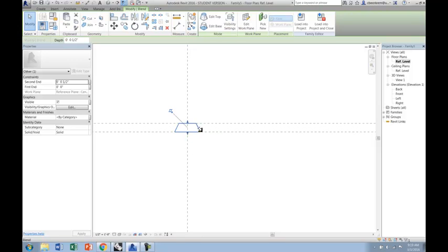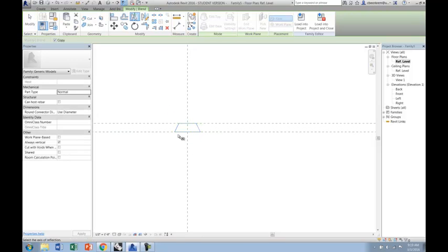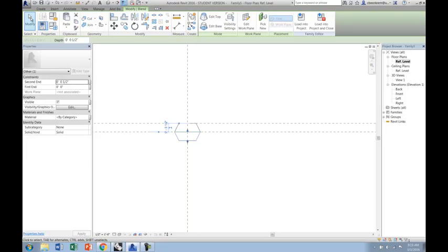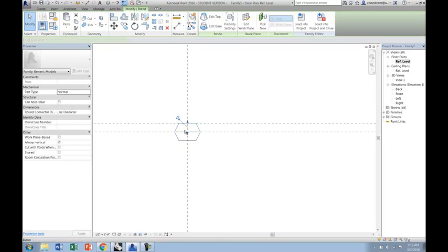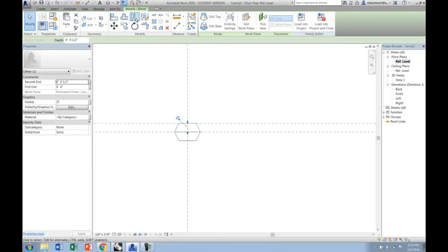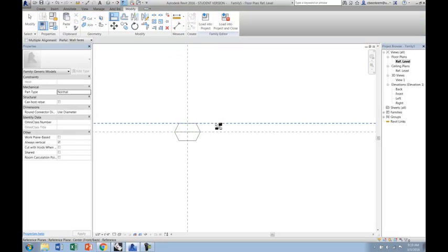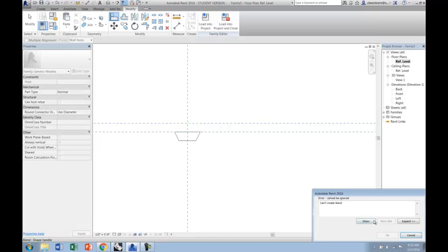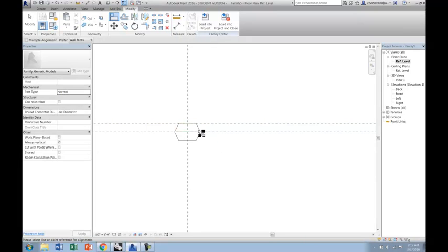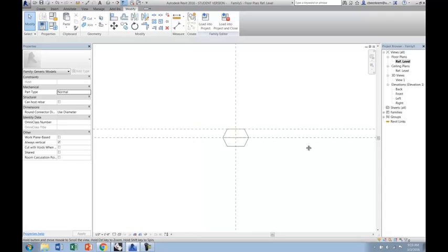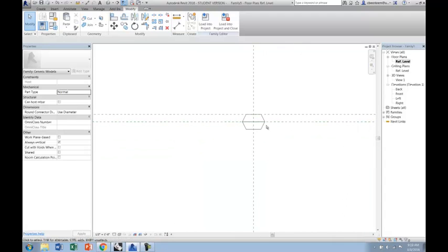So here's the first part of our knob. We're going to want to mirror this along that plane. And now we want to use the align tool, and we're going to use this align tool a lot. You're going to use that to make sure that first blend is snapped to the original plane. So we need to, let's see.